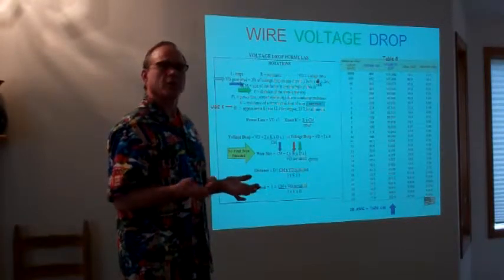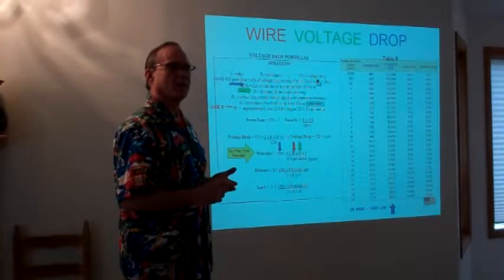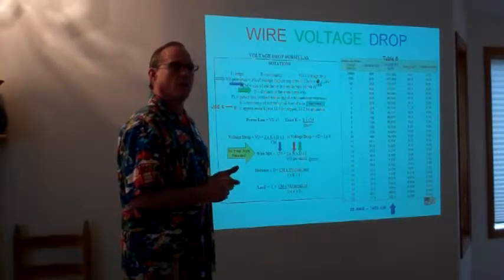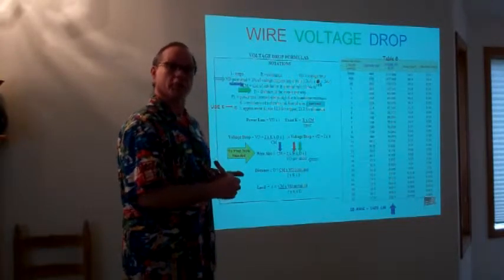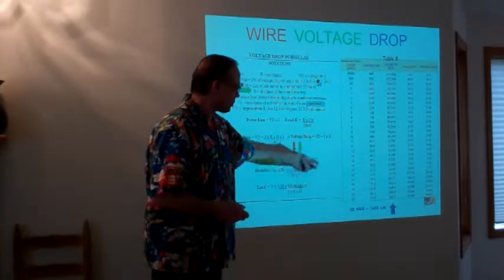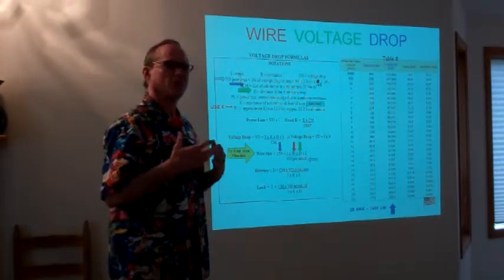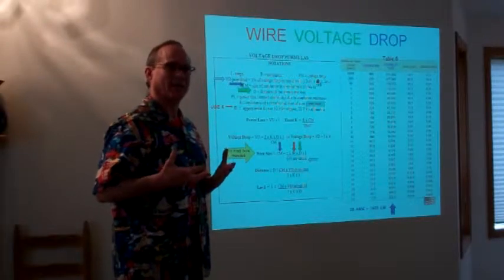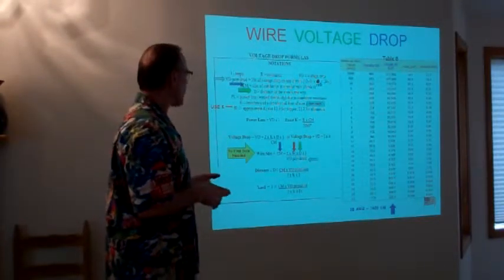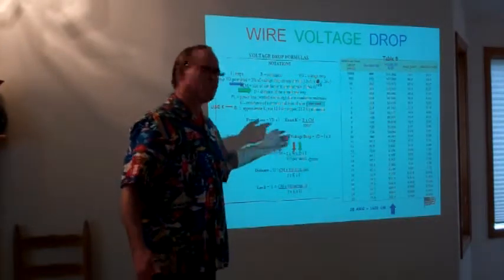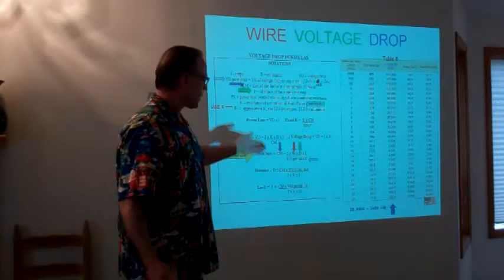Standard building wire we typically find is usually number 12, number 14, 16. We primarily will be using 18, 20, 22, and probably 24 gauge. And you can see that these are listed on here for us. The 22 and 24 gauge are probably going to be used with category 5 or category 6 cables, because that is the actual size that we typically find in those cables. We can do the same thing. This formula works for every kind of wire that we have. Okay, we can find out the size.